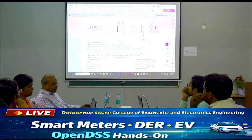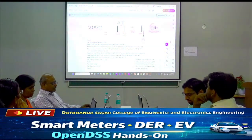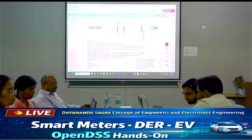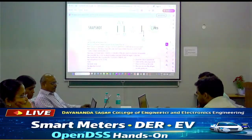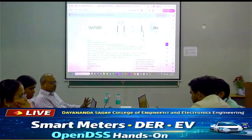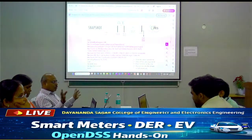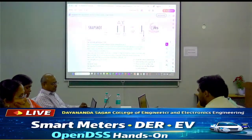And then you define the load. We define the load as load dot load 1, and then the bus it is connected to, which is the load bus, and it is 12.47 kV, 1000 kilowatts and power factor 0.95. So with that the load is defined. You can define a lot more about the load if needed, but this is a basic minimum definition.